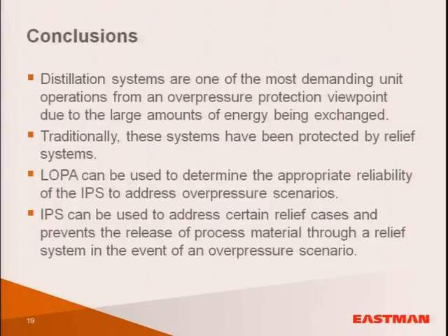So in conclusion, when we look at these distillation systems, it's a very demanding unit operation from an overpressure protection viewpoint and a relief design viewpoint because there are large amounts of energy being exchanged. Traditionally, these systems have been protected by relief devices and relief systems. At first, we looked at using some inherently safer technology, such as rating the column system above the vapor pressure of the components at the steam temperature.